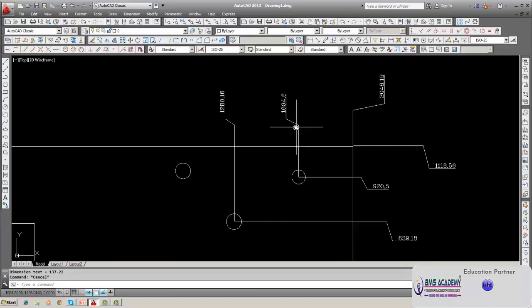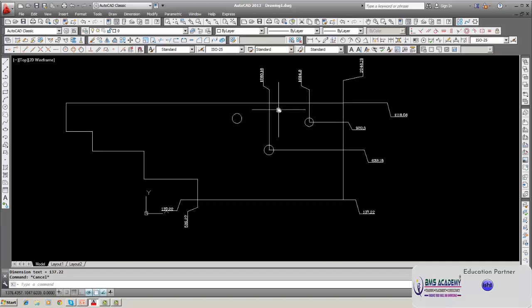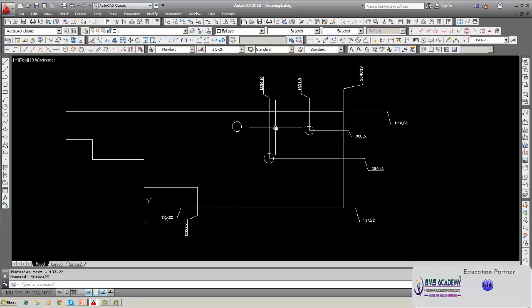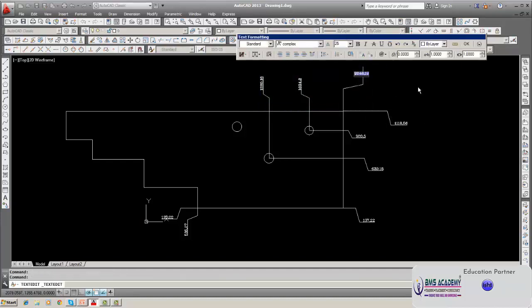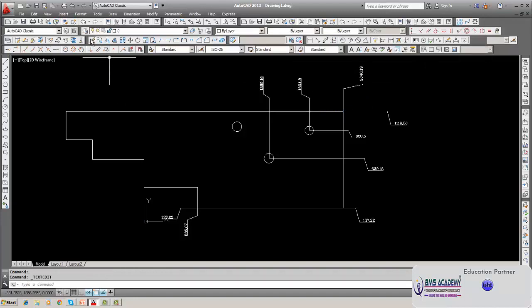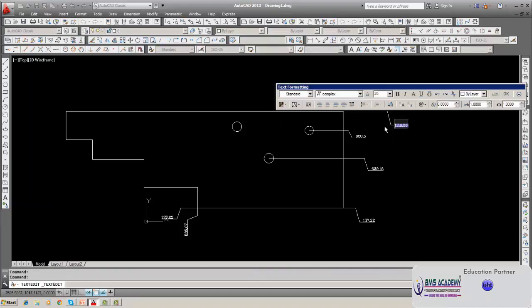So here what you have to do, for all horizontal dimensions, you have to deduct the values from this, and you get the distance. From here to here, you deduct the value, you get the distance. But this also needs some calculation to be done. So you want to avoid that also. For that, I will tell you what we should do. So this is also not a very easy method of dimensioning, even though it is a coordinate dimension. But you want the datum to be 0. For that, what we can do, we shift the component to the datum line, the center line.